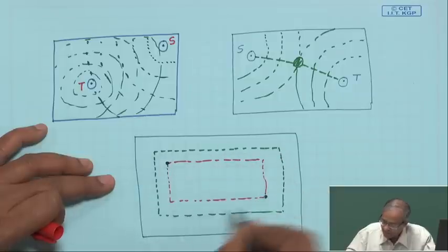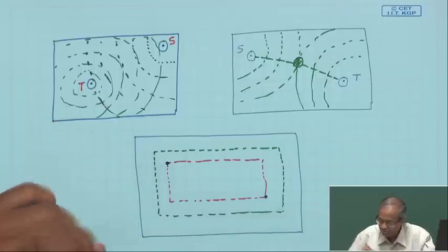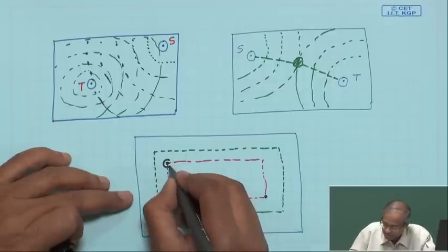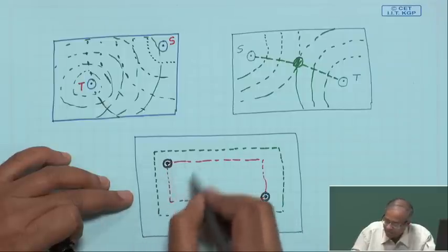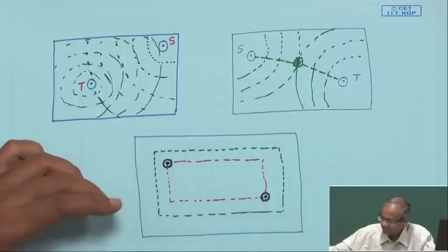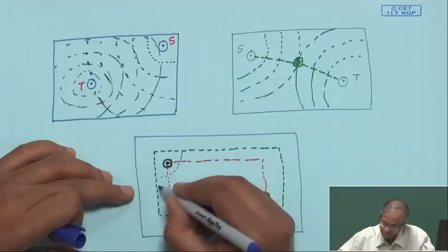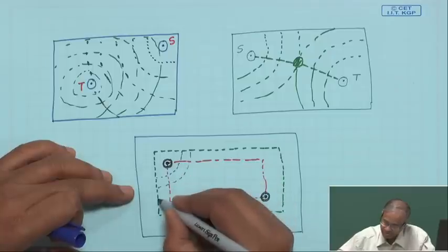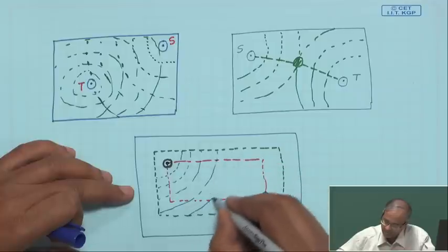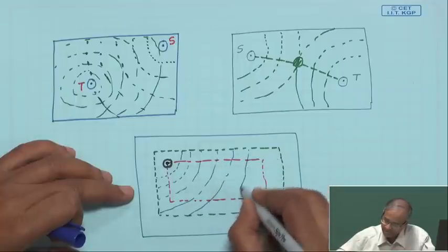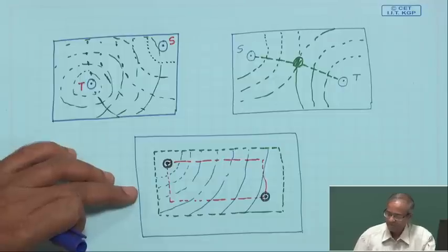You take a little more, because the idea is that when you generate the wavefronts from one point to the other, you do not allow the wavefront to cross this boundary, which means your wavefronts will only be limited to this rectangle. That means cells outside this rectangle will not be labeled. So, you are directly restricting the number of cells you are labeling, right.